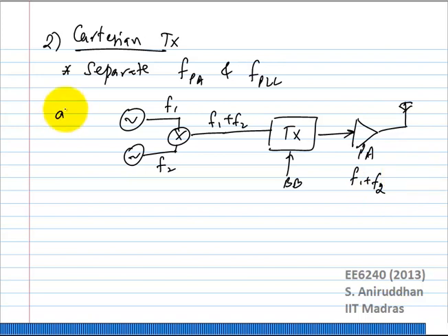What else? Anything simpler? We don't want to be designing like two PLLs. Okay, so one thing you can do, you can try to use a frequency divider to change the PLL frequency. Now what you are doing is you are actually moving the frequency away, but remember that if you use a frequency divider, the PA frequency and the PLL frequency will still be harmonically related. Okay, so one other very common solution is to, let's say, divide by 2 or 4.